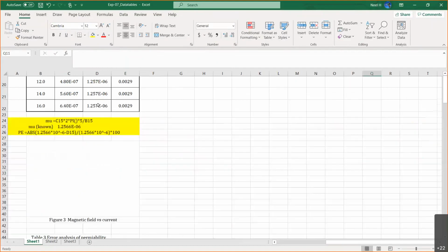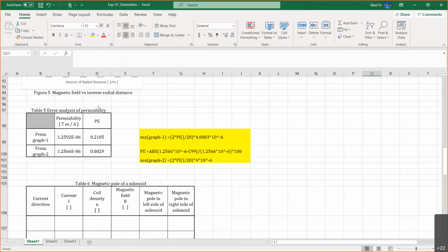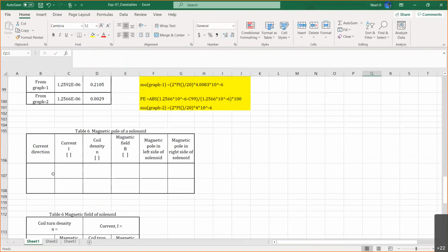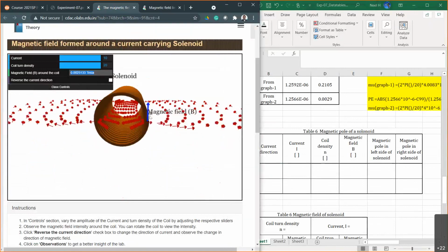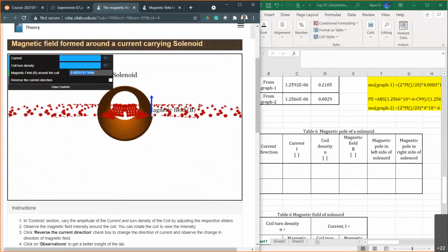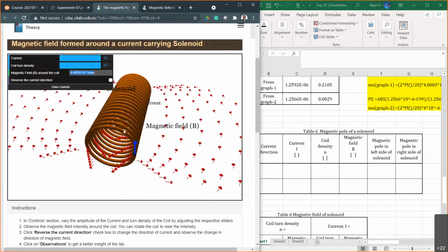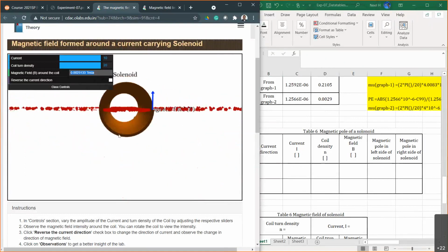And then let's take a very brief look at how the magnetic field is generated and what the directions are. So the current direction is relative to your observation. Remember, you're supposed to observe from that angle, looking inside of that cylinder. Then you can see the current is going upward and then round like that, from your right-hand side upward to the left-hand side. That is generally what we call counterclockwise direction, okay? Current direction is counterclockwise.